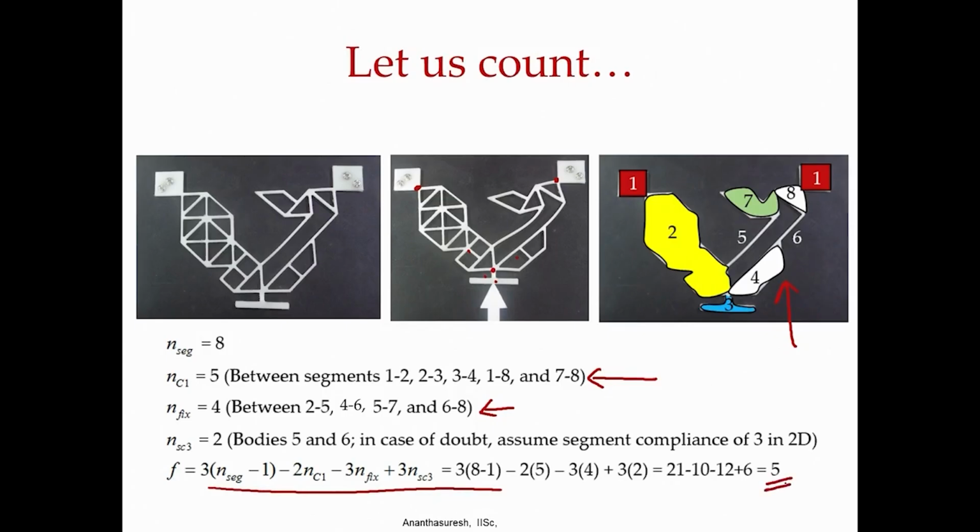When you have 5 degrees of freedom, we can actually count them. How do you get 5 degrees of freedom for this? It is supposed to be the force you apply here, and this moves in that direction in an amplified way, that is clearly 1 degree of freedom. But then nobody prevents you from applying a force in that direction, and movement also. You can hold it and rotate, those are 3 degrees of freedom.